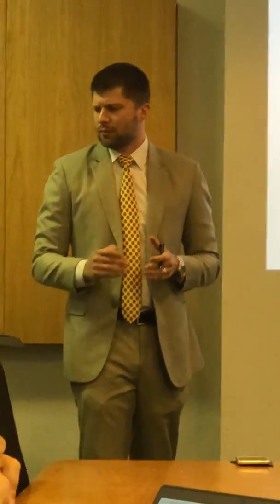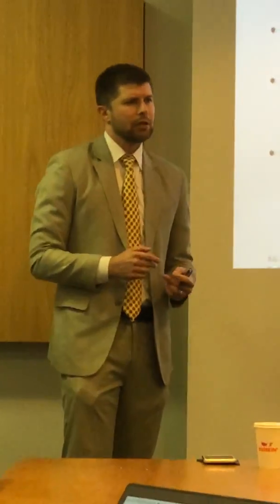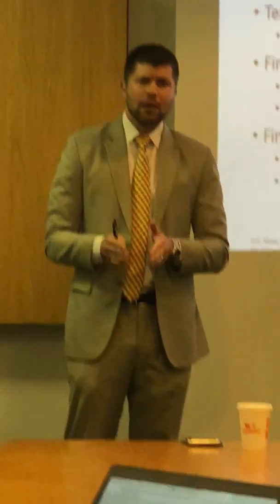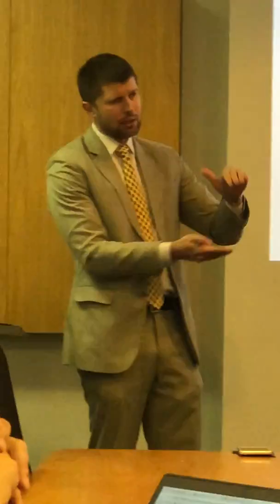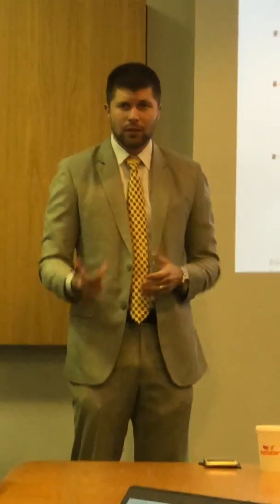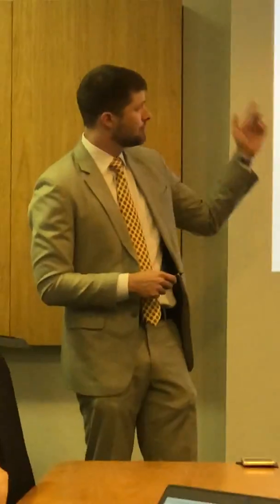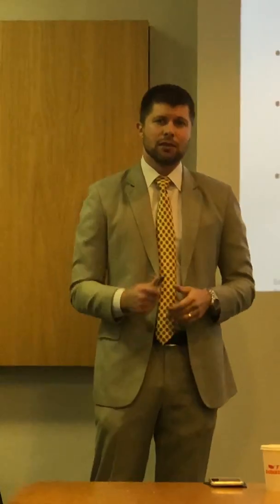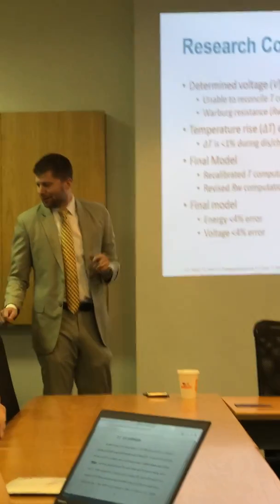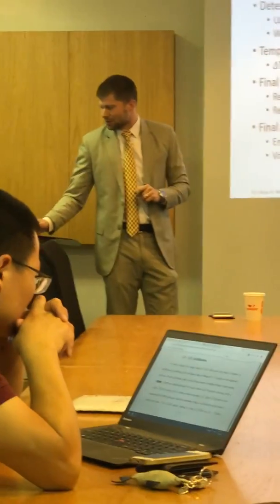But this initial model did not compute the cell's voltage properly. And we're going to see this is a big deal because your rudimentary battery testers look at the voltage. Now, of course, voltage doesn't change very quickly in a battery until the battery's about dead. But in a capacitor of any sort, voltage changes linearly as a function of the state of charge. So voltage is a really quick way to tell with these devices if it's charged or not. So we need to know the voltage if we're going to know how much energy the device can store.